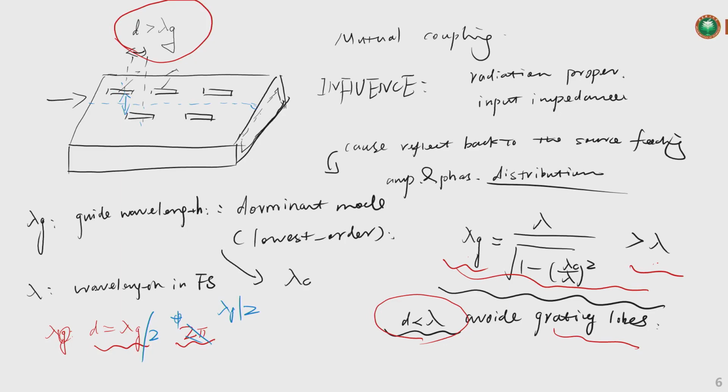They are positioned on their cut at both sides of the longitudinal axis, and you're going to have a contribution of half a wavelength, or pi of phase shift, and both together can be a total of one guided wavelength. This can help us avoid the mutual coupling.